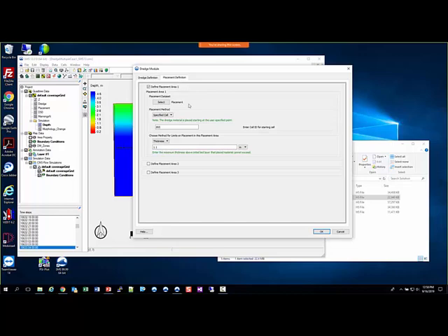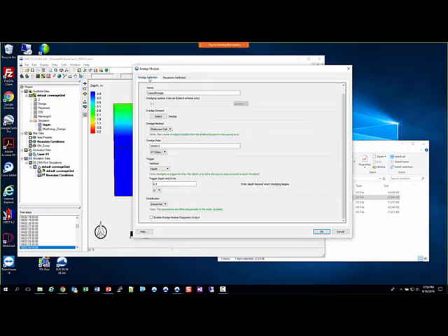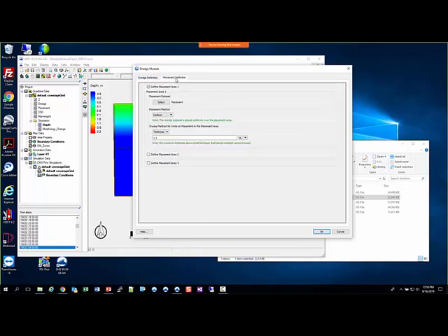So in the placement definition, the options, we also said, starting at a certain cell, but then you could also place the material uniformly throughout the entire area, and then every cell gets the same amount of material as the dredging is occurring, and then it goes up to a set thickness. And that's pretty much all of the options for the dredge module, and for dredging and placing material.